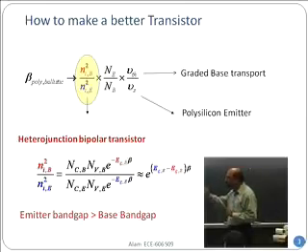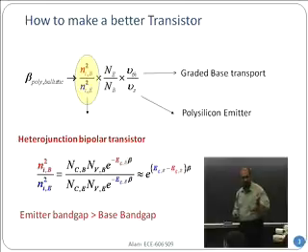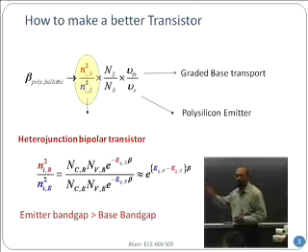But the main factor is e to the power of the band gap multiplied by beta, which is 1 over kT. The band gap for the emitter is E sub g comma E, and correspondingly you will write out the one for the base. You can see that the effective densities of state, more or less, are about the same, 10 to the power 22 or so, let's say.